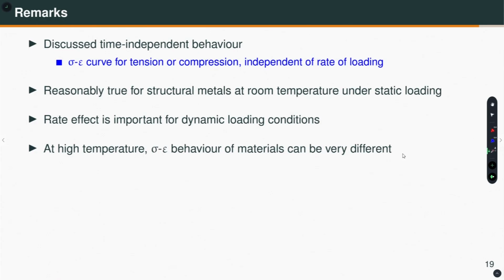So, what have we discussed in this lecture? We have discussed time independent behavior, sigma epsilon curve for tension or compression, which is independent of rate of loading. We have not considered any rate of loading, which is reasonably accurate for structural metals at room temperature under static load. But the rate effect can become important if you have dynamic load, especially let us say earthquake or blast. But structural steel do not show a lot of rate dependency.